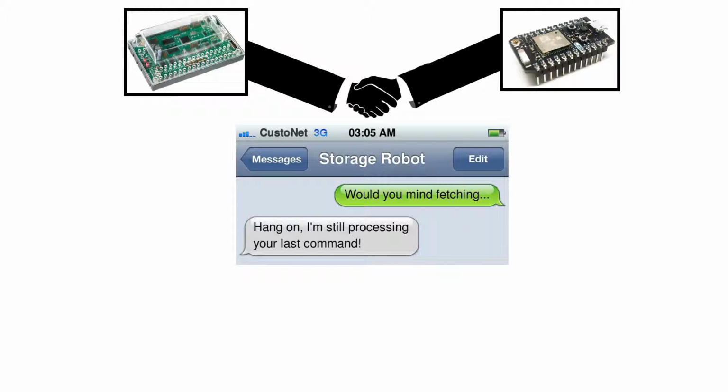I mentioned earlier that we need additional transmission control or handshake lines. Why? There are 2 additional requirements that we haven't taken into consideration so far. First, the Photon needs to know about the current state of the robot. More precisely, it needs to know whether the robot is able to receive and execute the next command. The second issue is a bit more subtle. The data and command lines might be set individually. There is no guarantee that they'll all change levels at exactly the same time, nor will they change levels instantaneously. There might be a transition phase where the levels are in an undefined range.